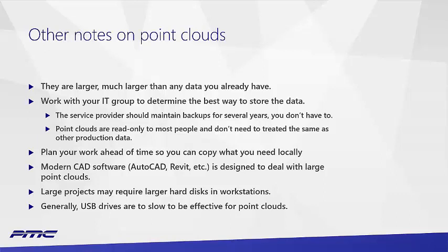Even though the data is huge, it still works very well in modern CAD packages. Whereas if you were to try to open a DWG that was 5 gigabytes, your computer would no doubt crash. But AutoCAD can use a 5 gigabyte point cloud without any problem at all, even on old hardware. Keep in mind, if you have a large project, something where it's a million square foot structure, you probably are not going to have a hard drive big enough in your computer, and you're going to want to address that before the project gets underway.